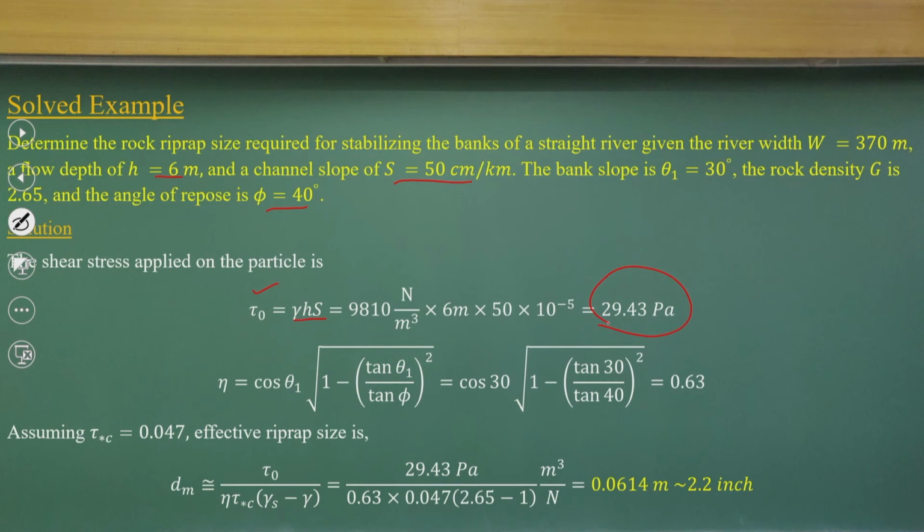And you can also compute that component, and finally, you can assume the critical shear stress value which we discussed earlier, that we can consider critical shear stress as 0.047, and for that you can substitute this value, then you can compute it.